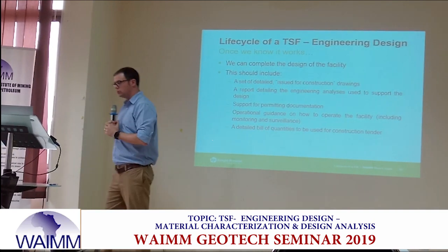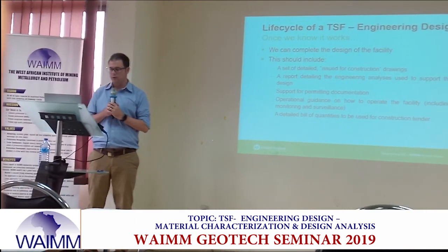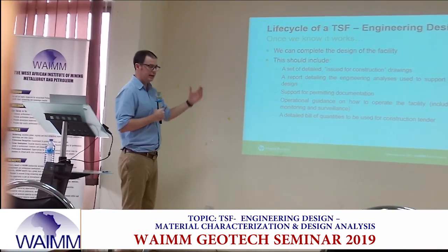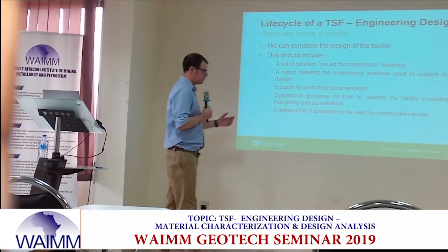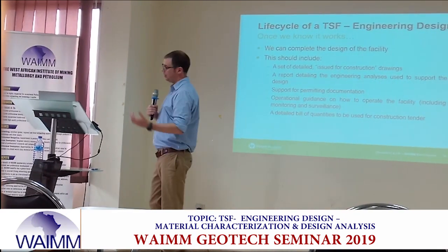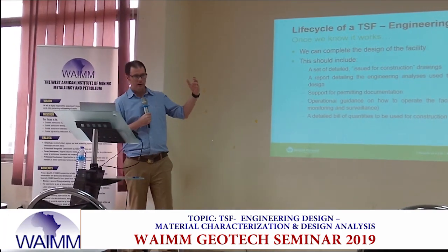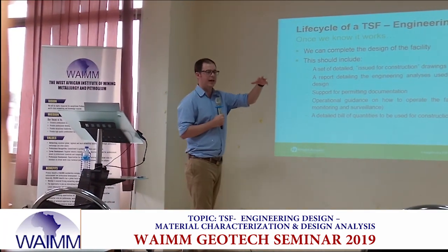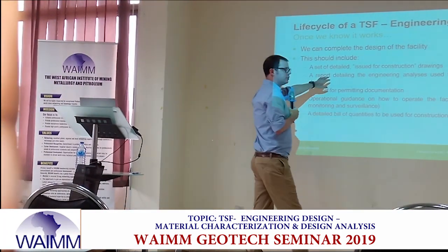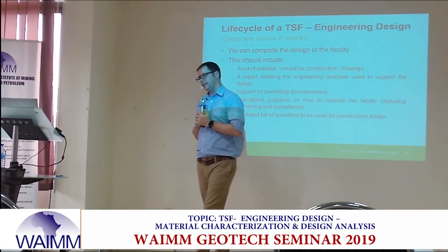We may do some support for permitting documentation from a geotech point of view, certainly from an environmental point of view we will. We should be working and thinking about operational guidance, operations maintenance manuals, operations maintenance surveillance manuals that help the owner and operator understand what did we think was going to happen? How did we expect you to operate the dam?